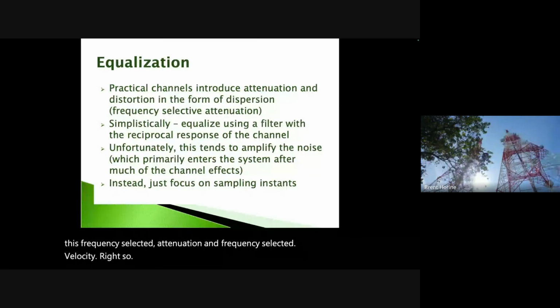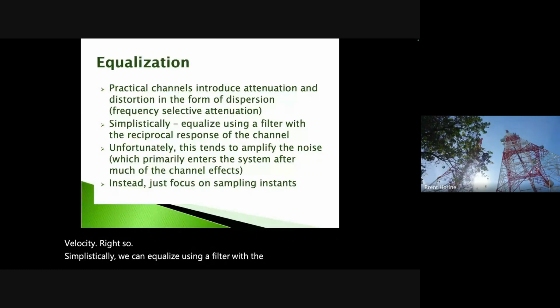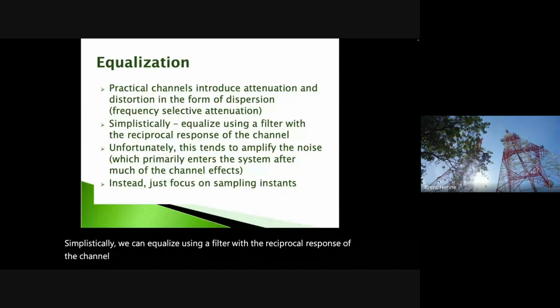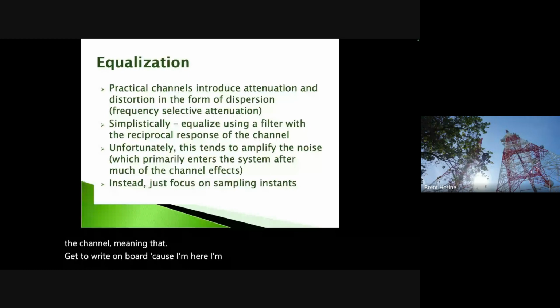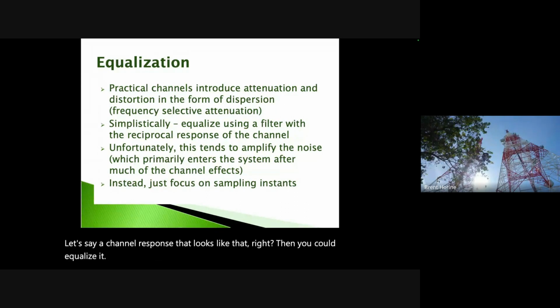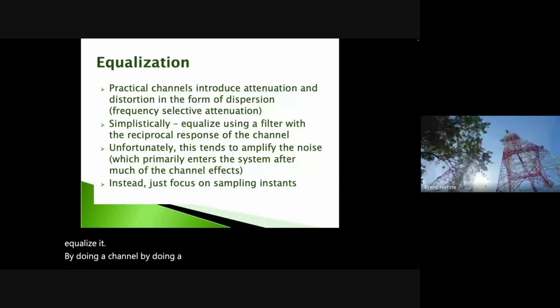Simplistically, we can equalize using a filter with the reciprocal response of the channel. I get to write on the board because I'm here, sorry to the people that will watch from home. Let's say a channel response looks like that. Then you could equalize it with a compensator that's the reciprocal of that.